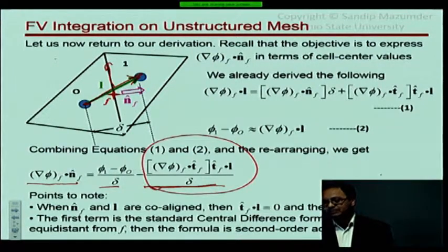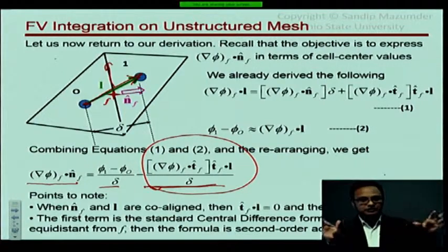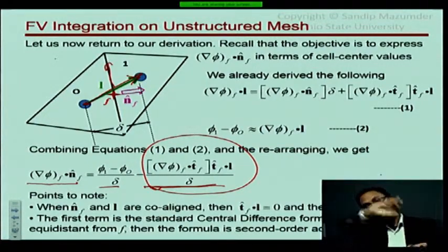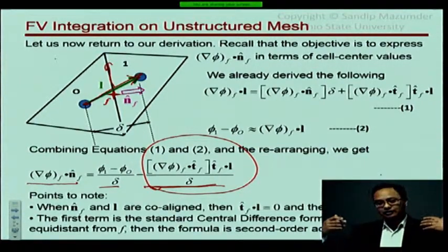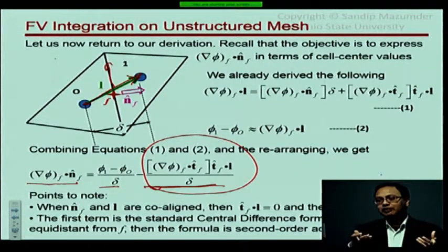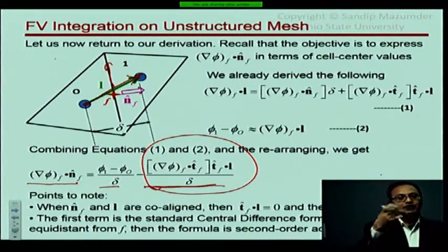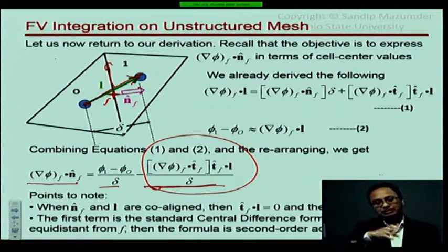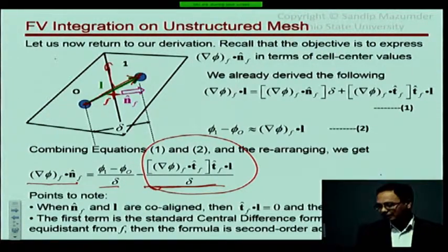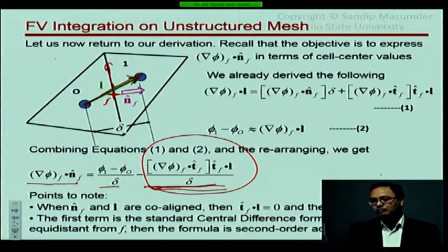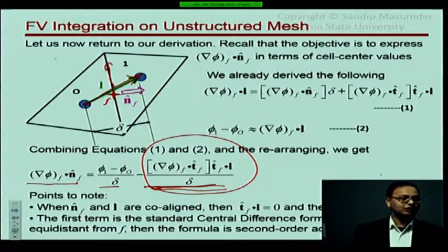So what happens is, once you write your discretized equation, you take that term and throw it over to the right hand side. It's kind of like your Gauss-Seidel scheme, where out of 5 terms, 4 of them you treat explicitly and throw them over to the right hand side. Same thing here. You can take this term, throw it over to the right hand side, and then solve your equations. Okay. Now what will that do? Obviously it will slow down your convergence. You've added more explicitness to your equation. Okay. So the smaller that term, the better off you are in terms of convergence.